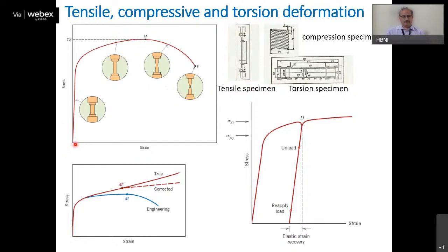And when you apply stress up to a certain region, it goes straight, and then plastic deformation starts. And then it reaches a maximum point above which the stress basically reduces. And this is called the tensile strength of the sample. Actually, ideally, this curve should not come down, but it comes down because of the way the stress has been defined.